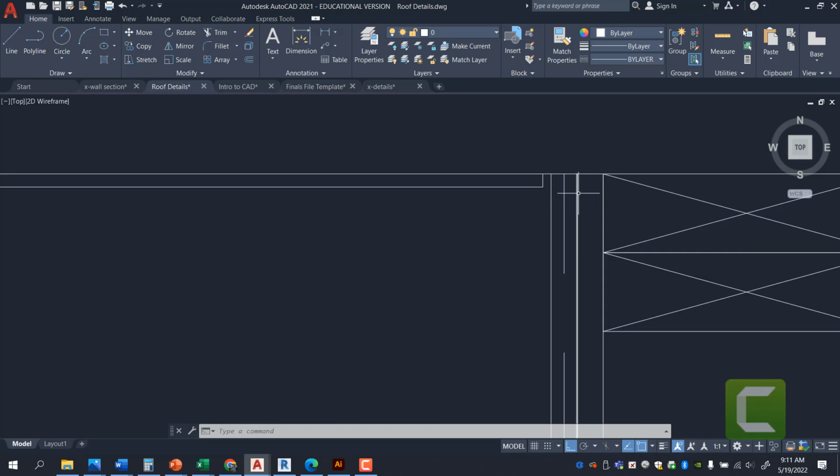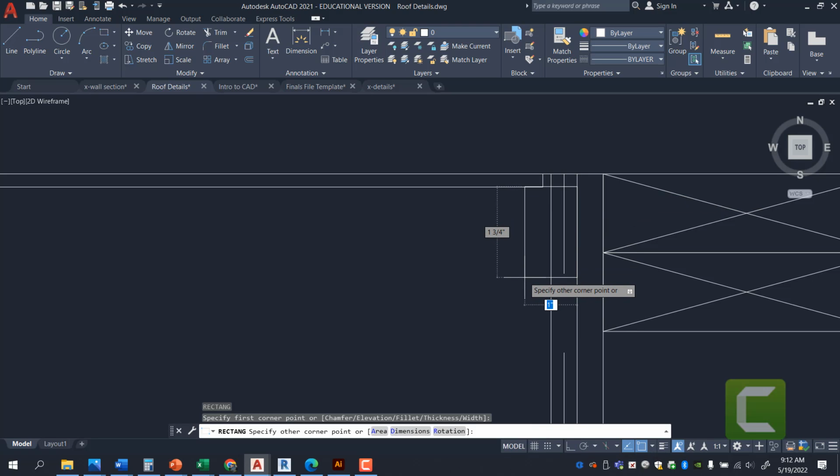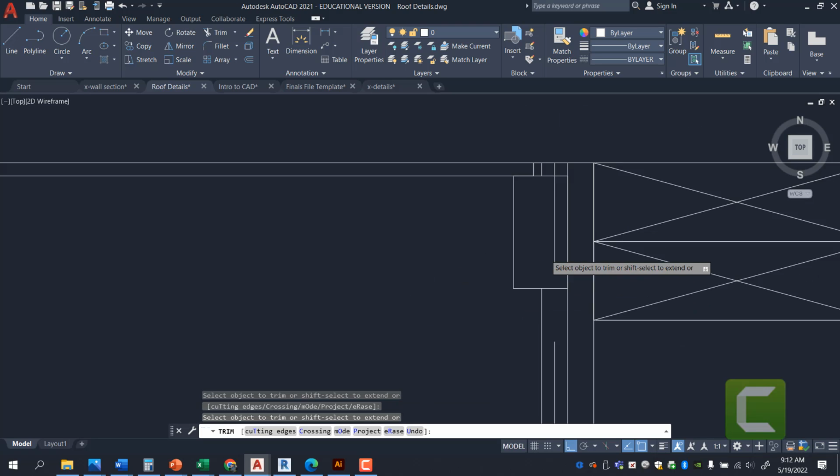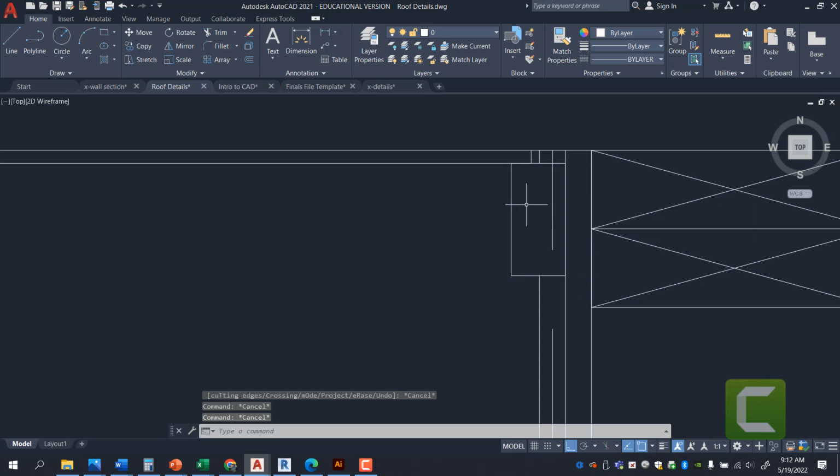But when it comes to how your trim dies, I highly recommend doing trims that do not overlap on top of your siding. Let your siding die into your trim.